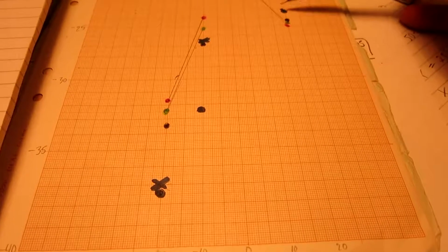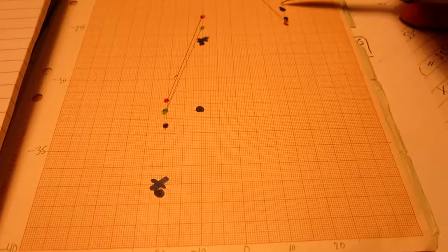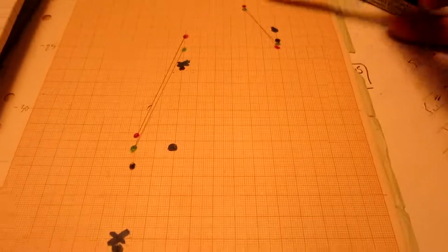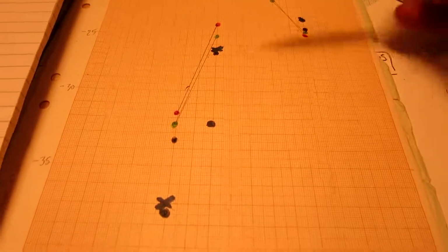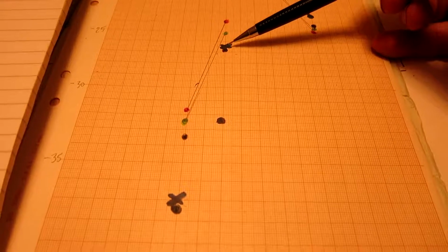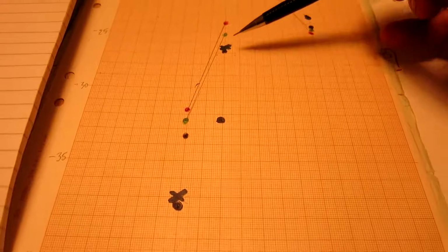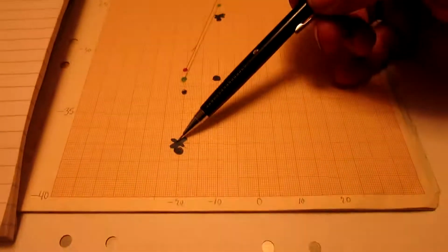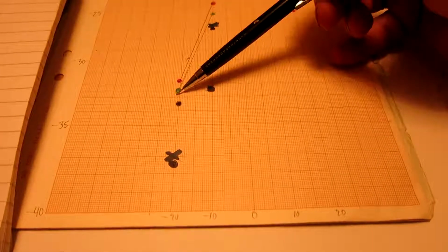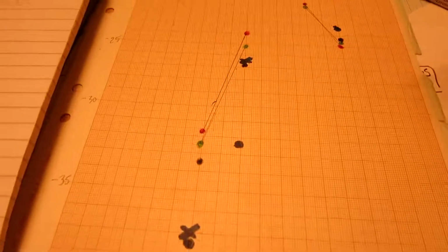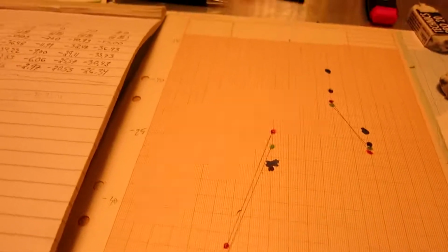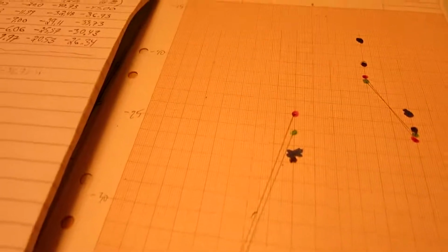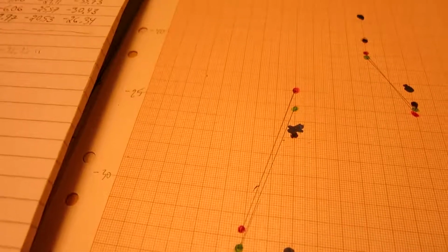And 6 decibels could be okay, but 3 decibels, that is more attenuated and less attenuated here, but there is a mirror image which is very strong, and the signal on the other side of the carrier comes here and here, so that is 3 decibels more power. And this is a non-linearity. I don't know what it would mean in an oscillator, but it seems dangerous to run as high as this, as the 3 dB setting.